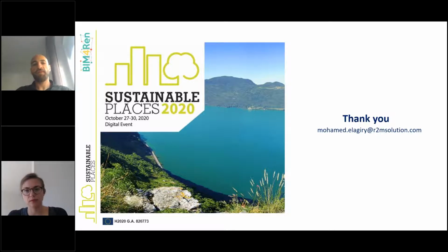So you have an output IFC file, but the thing is, an IFC file is something very complex. Imagine that you have a very big file with all the data possible. You cannot process all this data in each tool. So you just need to define what you need from this data for each specific tool. And that is done through the definition of the MVDs.